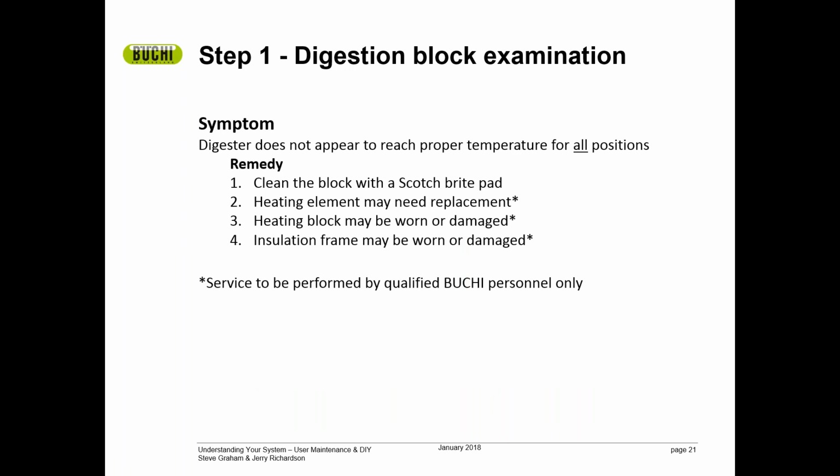Okay, when you're taking a look at your block digesting system, you can clean the block with a Scotch-Brite pad. Another place is the heating element, which may need to be replaced. If everything is clean and everything is fitting well, then there may actually be damage to the block or to the heating element, or the insulation on the frame may be damaged. In all of those cases, you need to get with Buki for a Buki service engineer to do that replacement work.